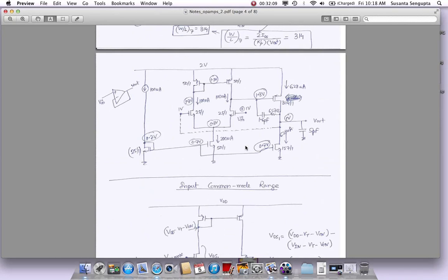And if you don't see exactly what is happening, the parasitic poles are making an effect, then you have to go back and iterate this design a little more. You have to change some sizes to reduce parasitic capacitances. You have to probably change, say, I can't just live with the same V on for all of them, and things like that. So you will go through an iteration, but this is the starting point. This is a good starting point before going to the simulator.